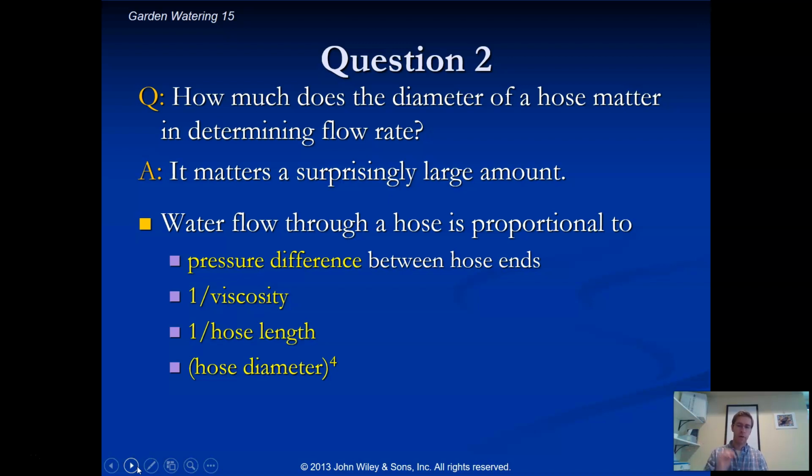He was putting in pipe that was 1/2 inch in diameter, and I asked him to stop, go back, and redo it with 3/4 inch. So only increasing by 1/4 inch in diameter, but that small increase was going to dramatically increase the overall amount of water flowing to our bathroom, and specifically to the shower.